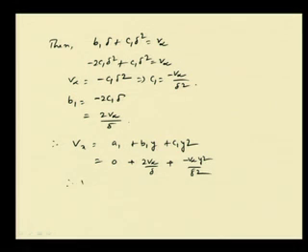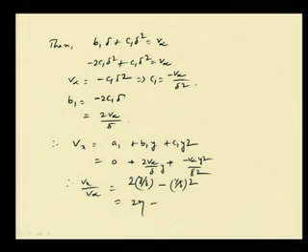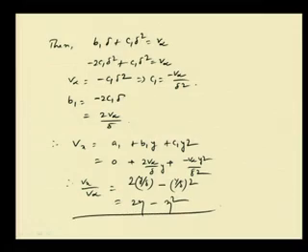So, we get V x by V infinity is equal to 2 into y by delta minus y by delta whole square. So, this is equal to twice eta minus eta square. This is the one kind of velocity profile we already listed in the previous table, whatever we have discussed today. Now, this is becoming the velocity profile.